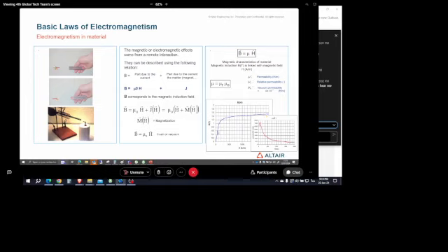We will see the intrinsic curve, which is the BH curve, the given characteristic of a given material, and you can see that it saturates. So when we apply an external magnetic field on this material, we increase the flux density, and at a given magnetic field value, we are going to saturate